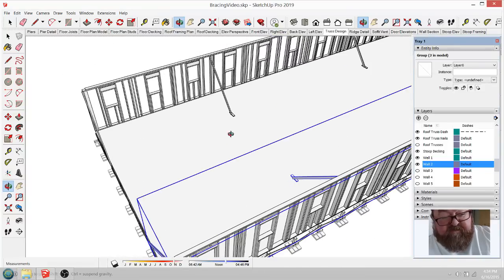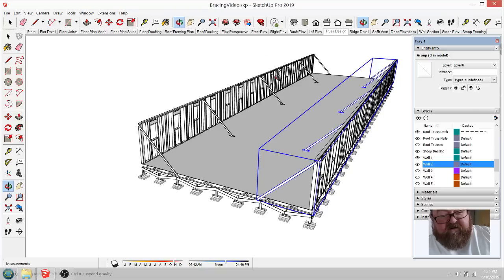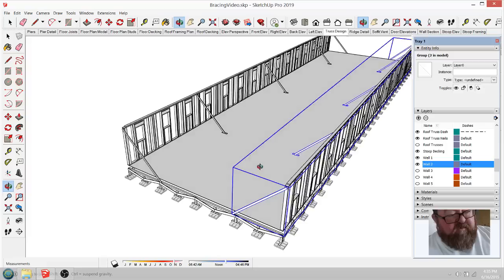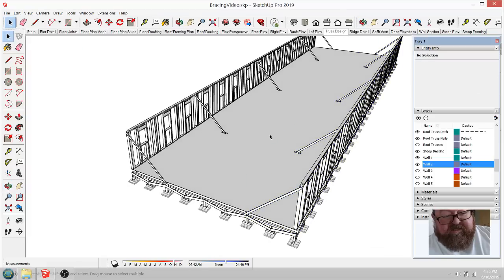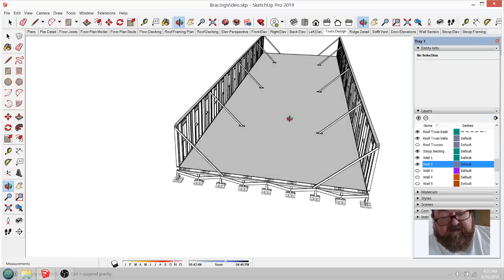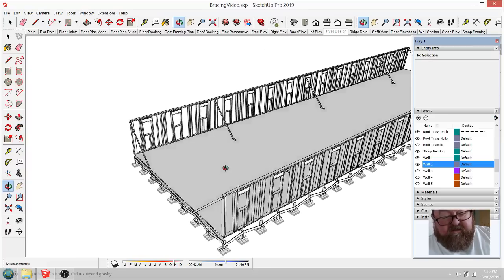These are semi-permanent braces. Until you get all the roof decking on and all the wall sheeting on, you're not going to take these braces off. This is the mistake you see, is people not looking at the bracing systematically. So now we're going to